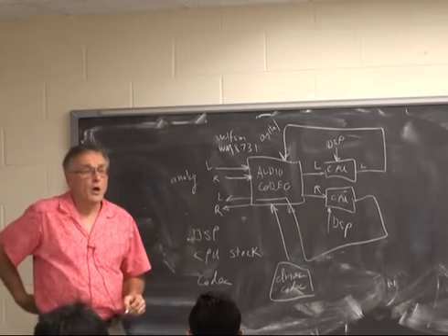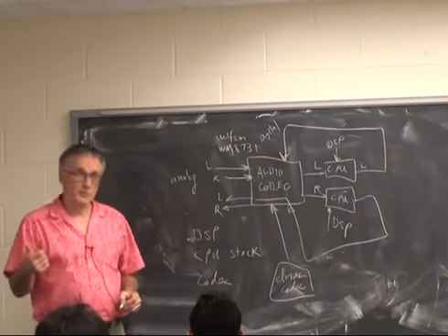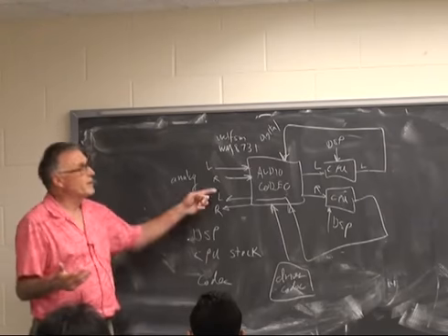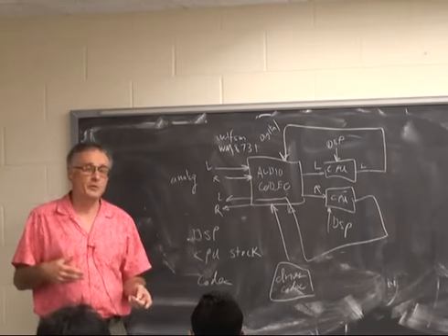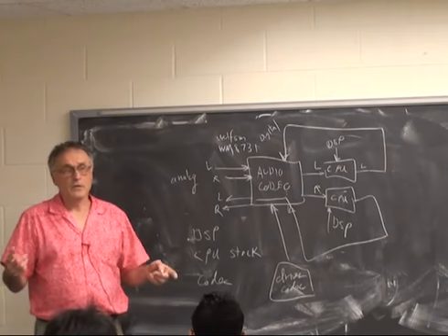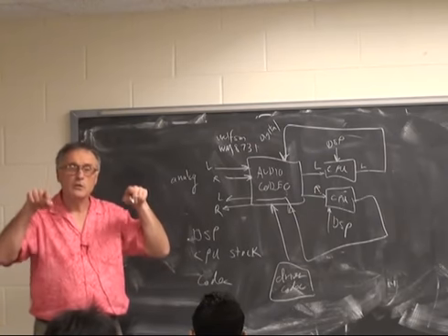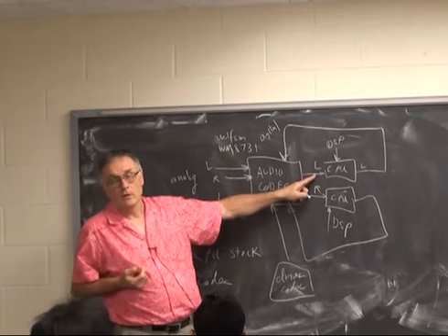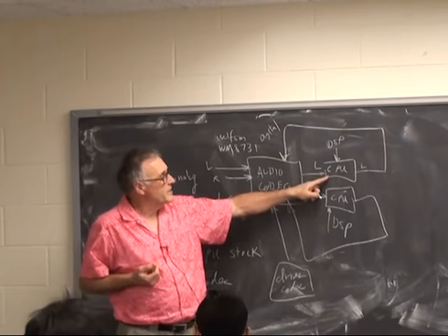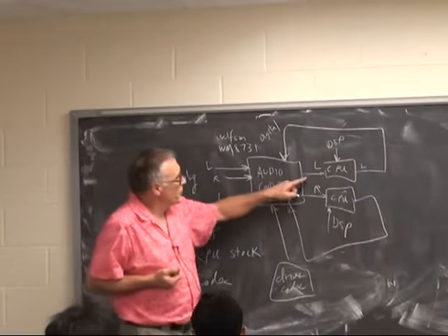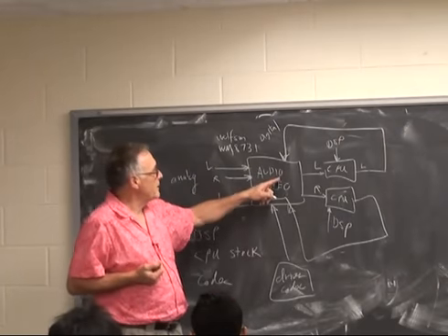It's going to say, what should the left channel volume be set to? What should the right channel volume be set to? What should the low pass filters for each channel be set to? Should the mic be turned on or off? Should either channel be muted? And a dozen other features of the codec. Then there's also going to be the high-speed digital audio channel, which blasts data at 48 kilohertz. I think there's a mistake in the code, it's actually 47.5 kilohertz between the CPU and the audio codec.